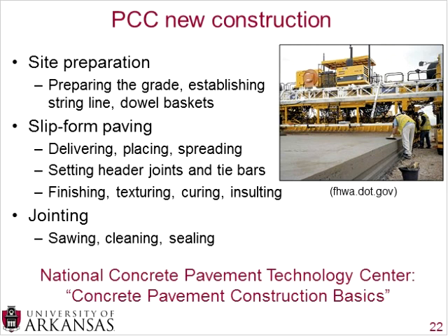You need to clean that out and then seal it immediately. If you do not seal it, materials can get inside that crack, water can get inside that crack, and over time that crack will get larger and it will deteriorate. And I point you to the National Concrete Pavement Technology Center Concrete Pavement Construction Basics, which is a nice document available online that goes through all these steps in more detail.